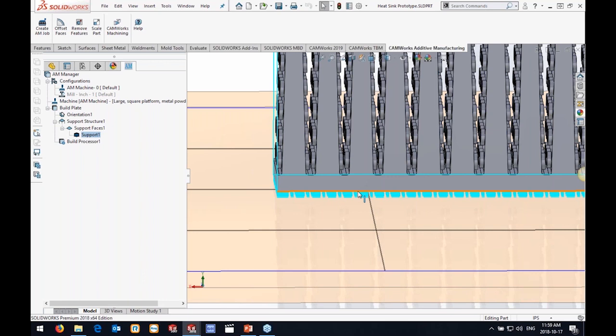Two of the printers that basically we have and we sell are those two types. Now, you might have multiple different 3D printers in your facility. You might want to run the same code but on different printers. Essentially, that's what our CAM tools do for our CNC equipment. Basically, that's what Materialize is doing in here. You have one method of setting the print job up, but you're outputting it to multiple different 3D printers based on the build processor, or basically the post processor for the actual G-code type thing.